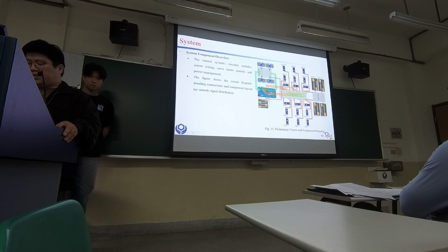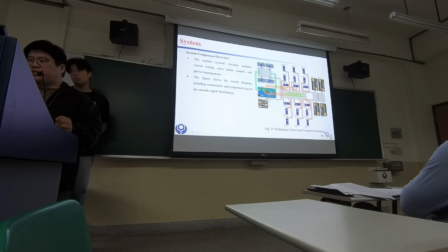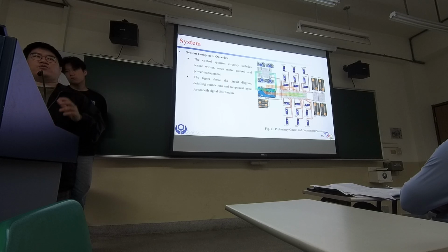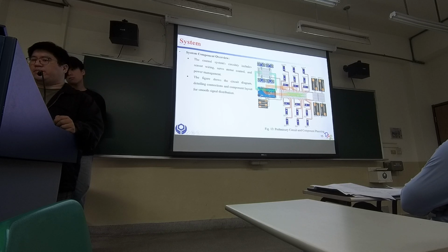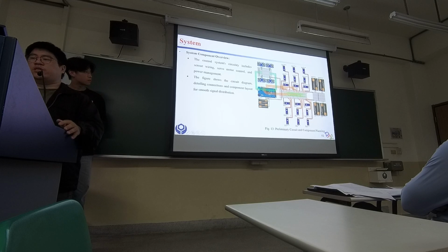Okay, so then we also generate the Arduino system diagram layout. In total, we will need four ultrasonic sensors, and then we need 18 servo motors for 6 legs, 3 for each one, right? So 18. The servo motors will be MG995. And we use an Arduino board to control the whole system.